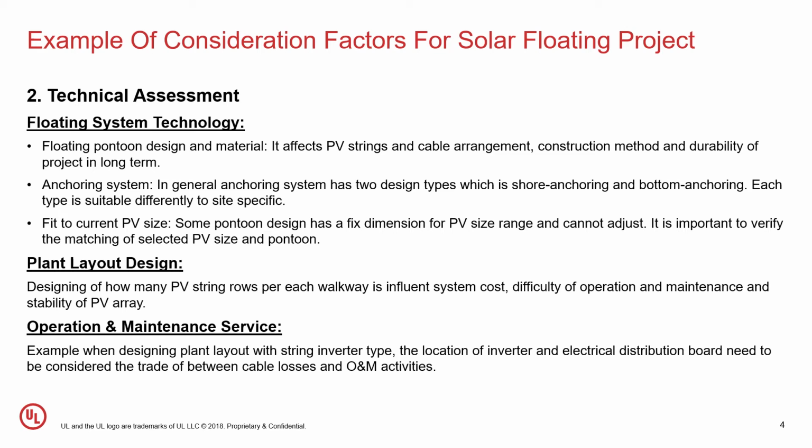And another factor that we see is very important also, but many people most likely forget when they start the project, is to check that your PV panel size and support pontoon size are matching.